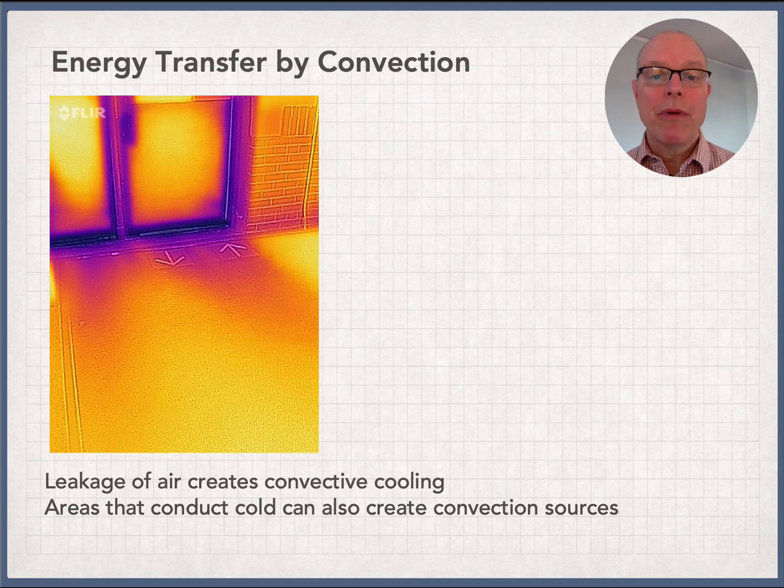We're going to wrap up right now with a real life picture taken with our actual FLIR cameras in the cafeteria at St. John's. What you can see is a couple of kinds of energy transfer going on. If you saw this purple region and thought the door is cold on the edge, you're right. Those doors, actually most metal doors, have insulation, some kind of polystyrene plastic in the middle, that does a decent job of blocking heat flow. The edges are just metal, and metals conduct heat.